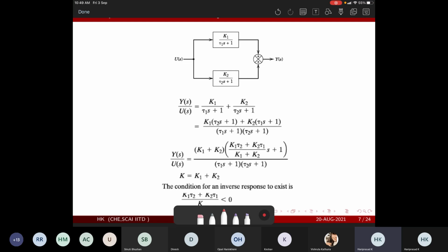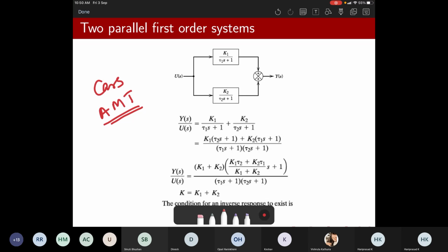So I don't know if you are trying to drive cars with automated manual transmission, which is called AMT. It's not the CVT type of car, but the AMT type of car. In AMT there would be your gears, of course, and an algorithm that is used to automate it, not really a continuous transmission. It is a manual transmission, and you made it automatic. So when you drive, let's say you are driving at 40, and you suddenly pedal your accelerator to increase the speed. The first observation that you would really see is a decrease in the speed.